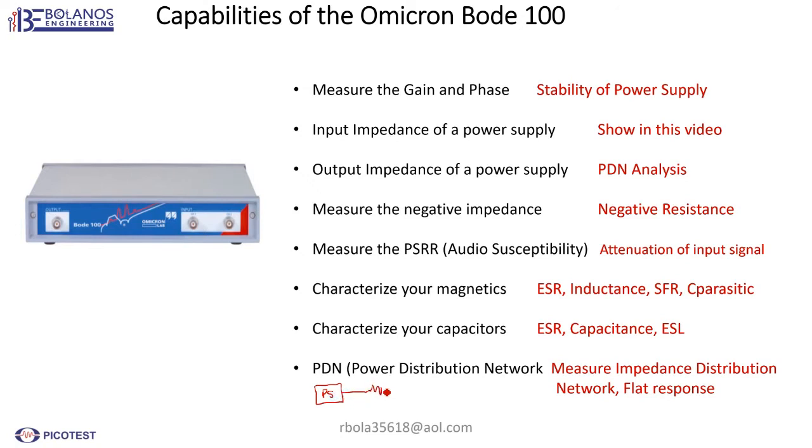The trace is going to have some resistance, and if it goes through vias and the trace, you're going to have some inductance, and then there's some board parasitics, capacitance, and then your connectors and so forth, and then you'll have your bypass capacitors. So all of this is a network, okay? And by the time it comes to your FPGA, you actually have series and parallel connections of capacitors and inductors.